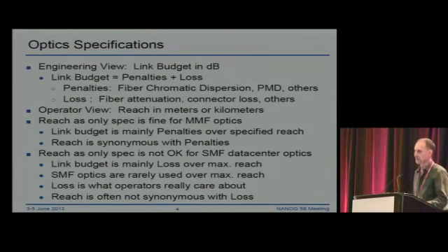But as we move into single mode interfaces, it turns out it's not sufficient just to talk about reach, because the link budget is mainly loss, and almost no one deploys the maximum reach. So even though the single mode interfaces you all use are 10 kilometers, there are very few links that are 10 kilometers. NANOG, in fact, supported the IEEE a number of years ago with a survey, and there are very few reaches above 5 kilometers. So reach is not synonymous with loss, and in actuality, what you care about for single mode is the loss.